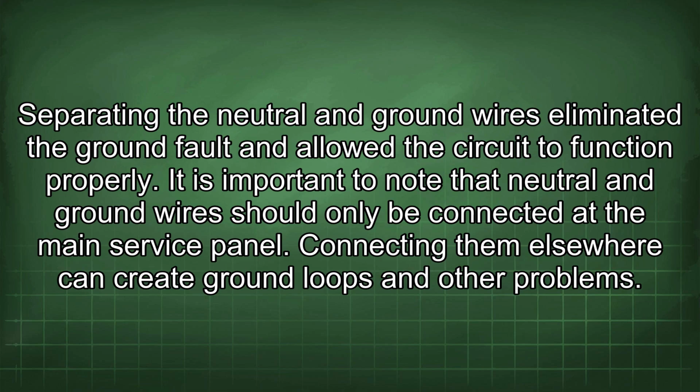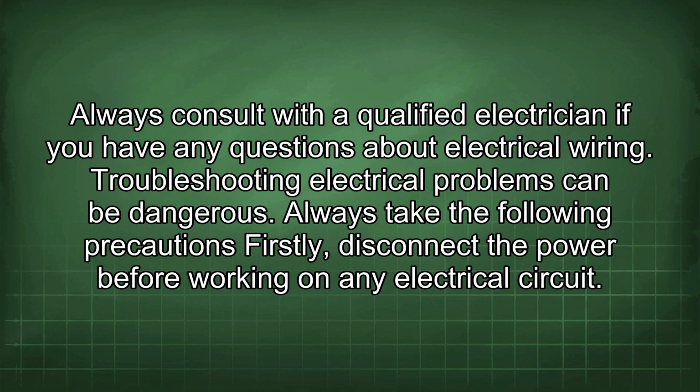It is important to note that neutral and ground wires should only be connected at the main service panel. Connecting them elsewhere can create ground loops and other problems. Always consult with a qualified electrician if you have any questions about electrical wiring.